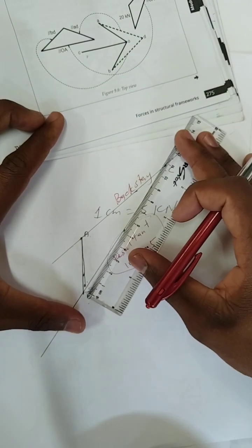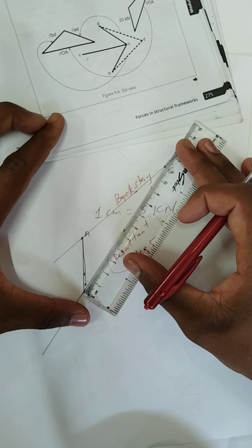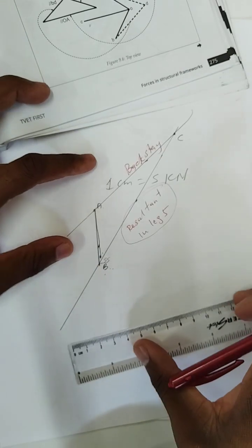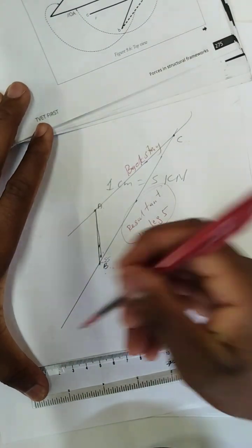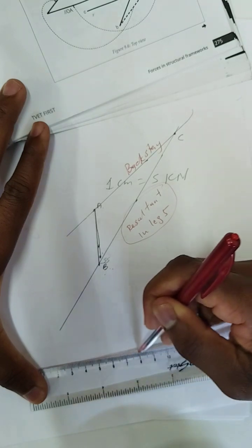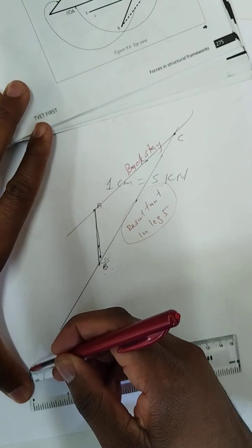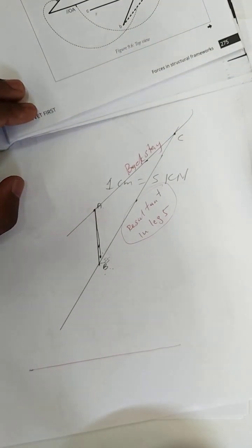So to get the force that will be carried by each member, you do this. You measure this length from here to there. In my case, it's 11 centimeter. Then you come here, draw 11 centimeter from here to there. I'm just doing a rough thing here. 11 centimeter like that. After that,